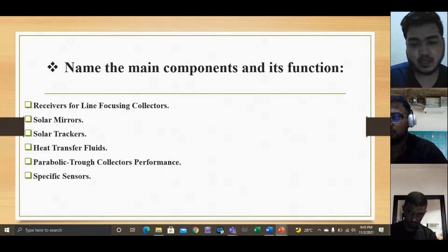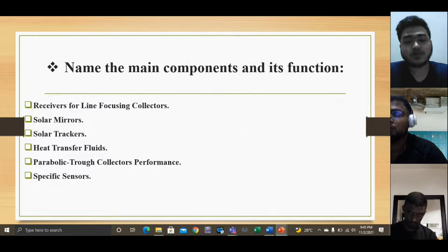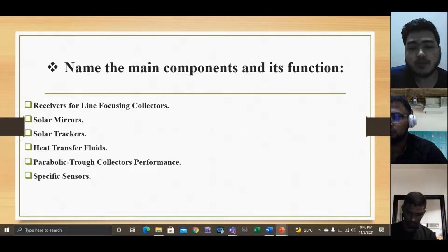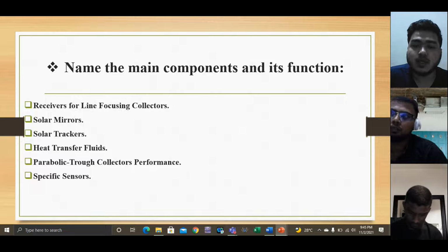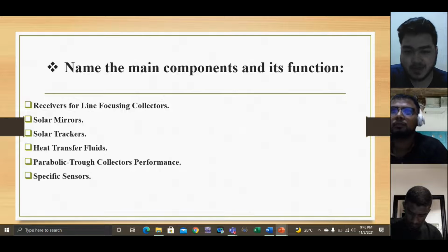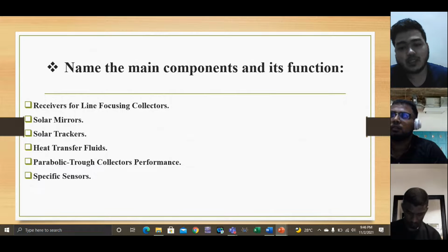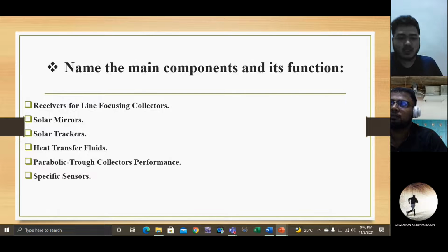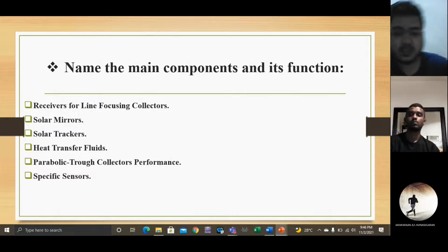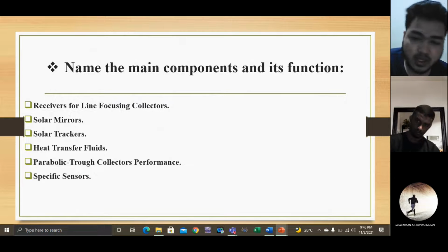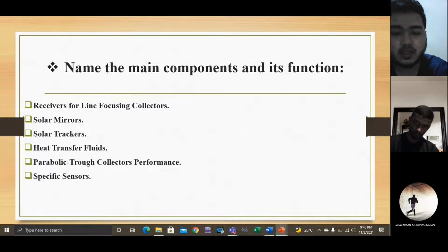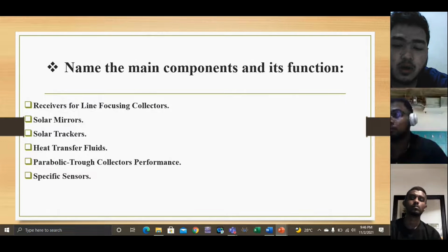And lastly, the specific sensors. Sensors used in solar thermal power plants are common sensors widely used in industry: thermocouples, Pt100, flow meters, and others. All of them have their own standards to secure quality. The application with concentrated solar radiation implies some good practices or requirements in the entire sensor quality chain, from manufacturing to installation.